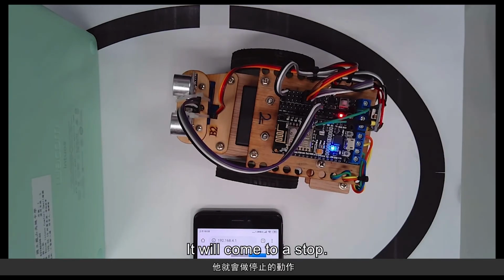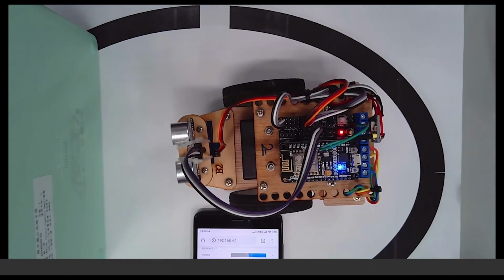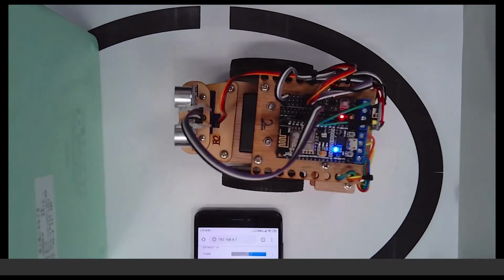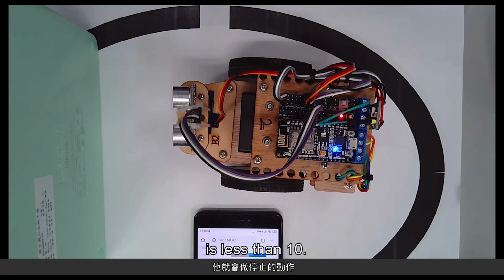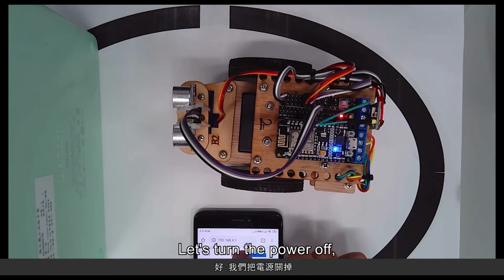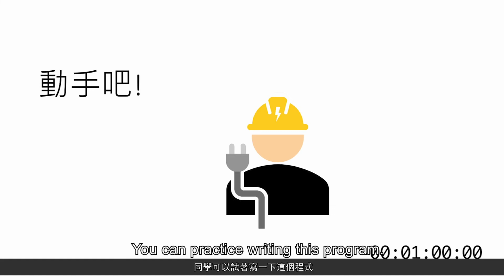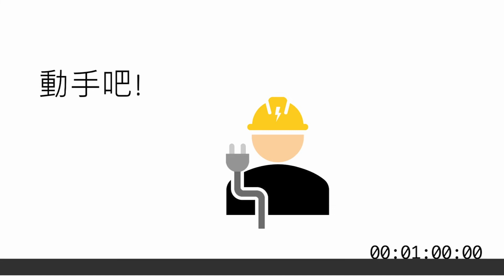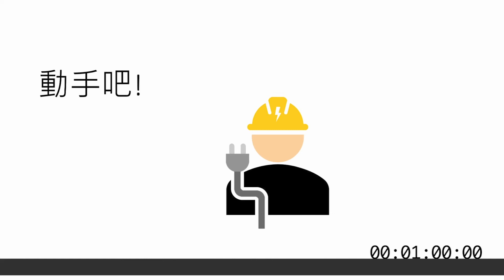It will come to a stop. We move it backwards and it will continue to move. It will stop whenever the distance is less than 10. Let's turn the power off. Let's keep moving. You can practice writing this program. Let the vehicle stop at a distance of 10 centimeters. Practice a little bit.